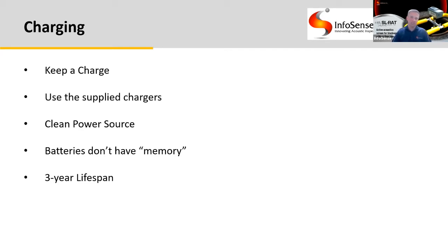The chargers are designed to not overcharge the batteries, so there's no harm in leaving them on chargers for long periods. Again, it's important to pay attention to the temperature range. The battery manufacturer recommends the ambient temperature during charging stay within 32 degrees to 100 degrees Fahrenheit.